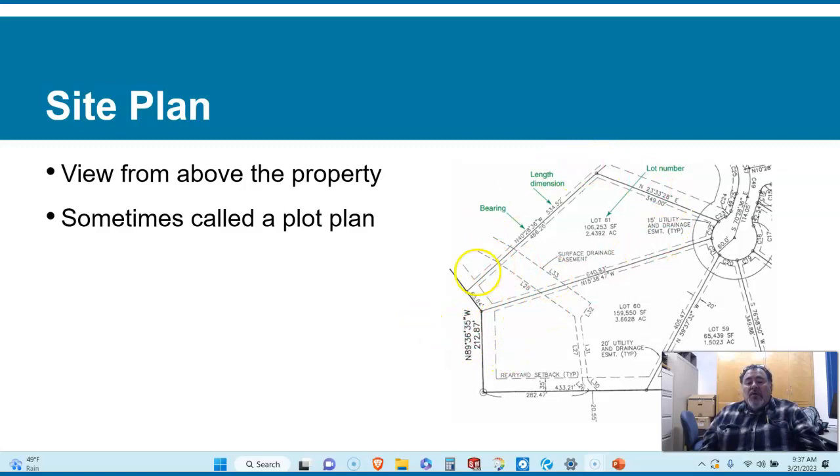And so you can see, it's a surface drainage easement. So this area has been designated for like a low area, and you can see it kind of crosses between other properties. So drainage, water can drain in this direction and meet in this little low spot. From the back, it meets in the low spot, and then it moves its way and travels down this little established corridor or a little valley.